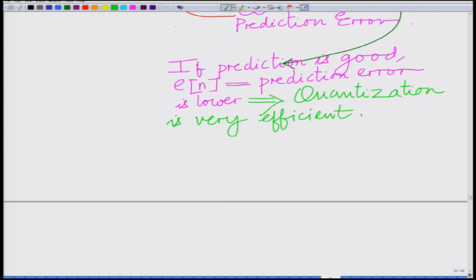Now, eq[n] is the quantized prediction error. Now, mq[n], the reconstructed signal, is similar to delta modulation. It is simply your mp[n], the prediction. Remember in DPCM this is simply mq[n-1]; this is mp[n] plus eq[n].